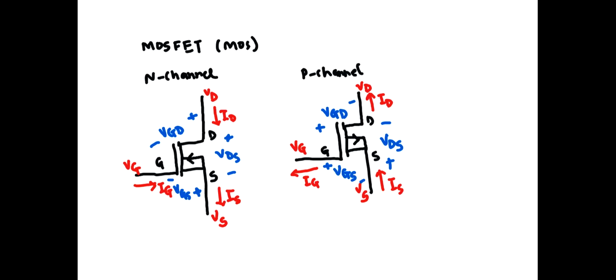Okay. Now, there is some terminology for the MOSFETs. We say that the gate current IG, let me use different colors for better understanding, is approximately 0 ampere. Why? Because for a MOSFET, metal oxide semiconductor, the gate is insulated so that the input current is negligible.